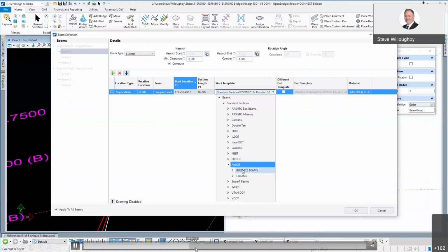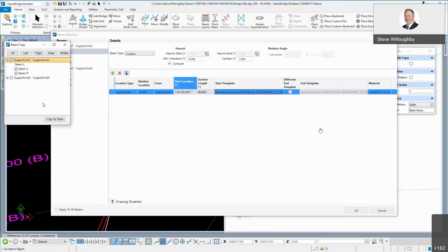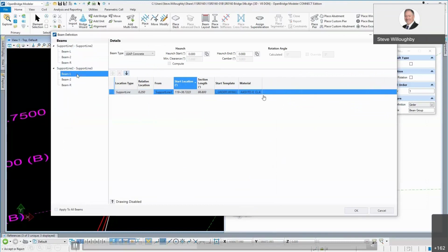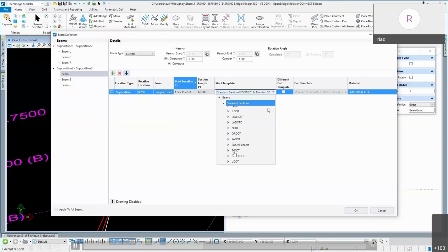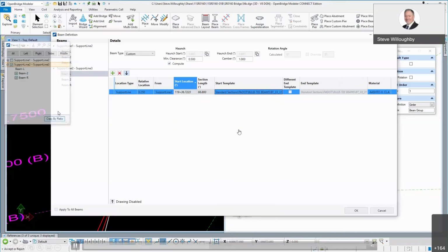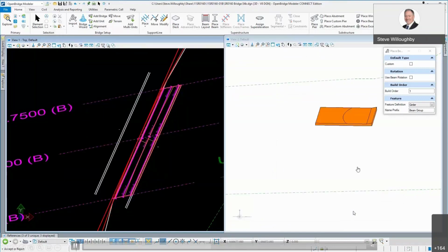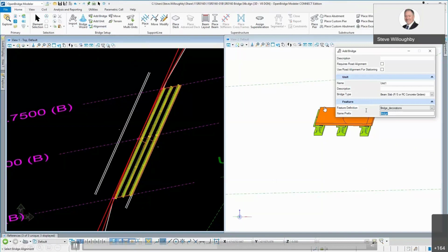So we'll go into the beam layout now, go in and select the different girders for each span, just like we did before, but now we have just these 3 beams here on span 1 and the same on span 2. So we'll copy that one for all the beams in span 1, and then I'll do the same process here for span 2 with that shorter girder. So we'll click on through this, go ahead and copy that to all the other beams out there, select OK and let it model them. And when it gets done, we'll be able to see that sure enough, it did allow us to have that beam flange partially exposed there. So again, this goes back about 3 or 4 versions of the software when this was first enabled.